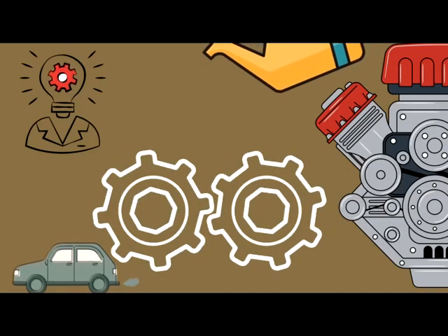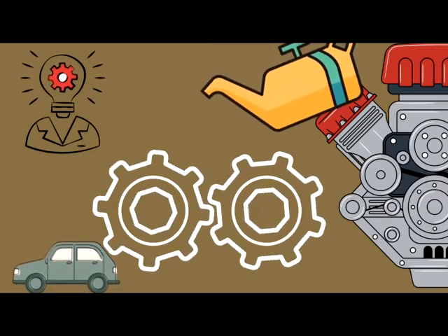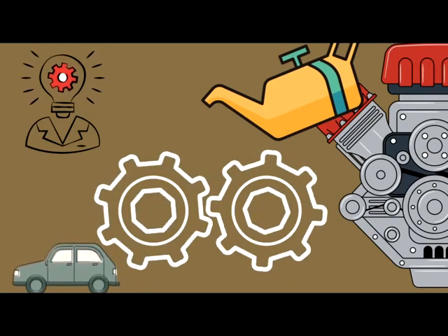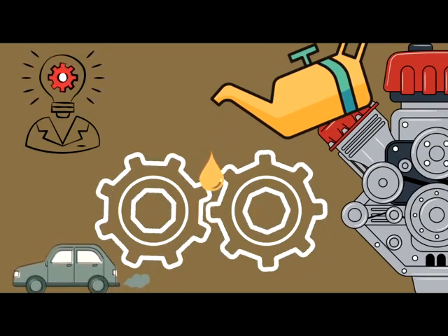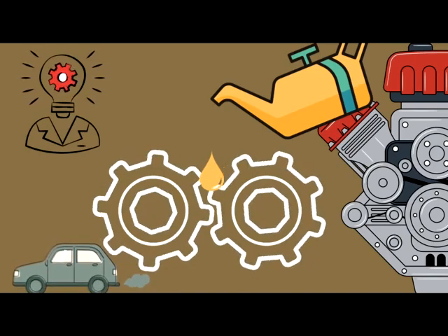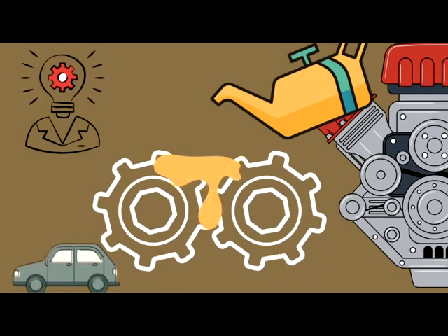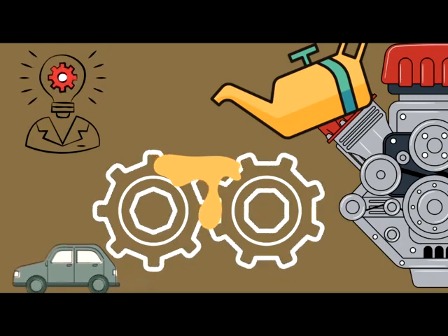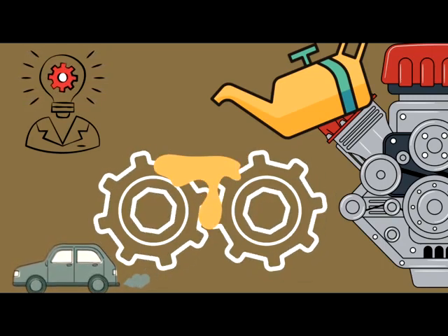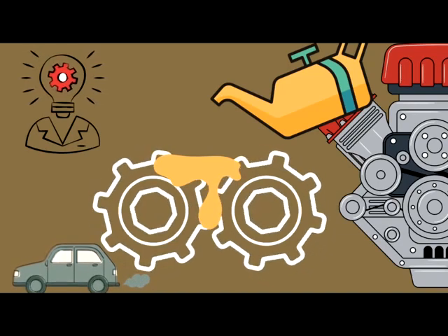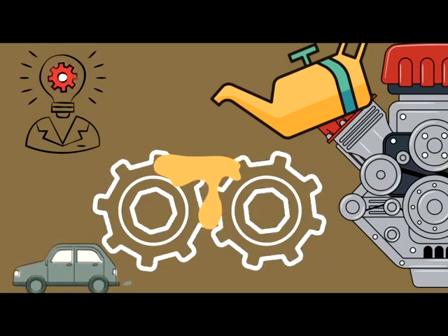In the engineering world, viscosity is essential for lubrication, which is the reduction of friction between moving surfaces. Different lubricants have different viscosities, and the choice of lubricant for a particular application depends on the operating conditions, such as speed, pressure, and temperature. For example, a high viscosity oil is used in a car engine to lubricate the moving parts, while a low viscosity oil is used in a bicycle chain to reduce friction and wear.